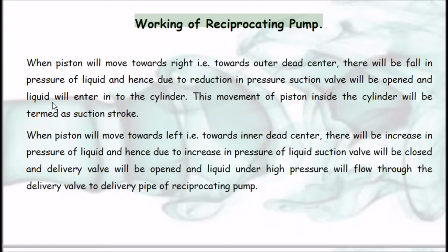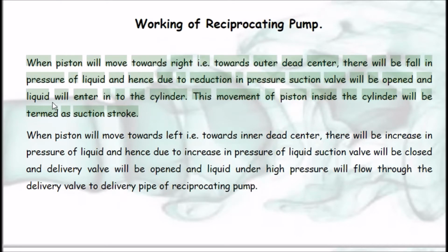Working of reciprocating pump. When piston will move towards right, i.e. towards outer dead center, there will be fall in pressure of liquid and hence due to reduction in pressure suction valve will be opened and liquid will enter into the cylinder. This movement of piston inside the cylinder will be termed as suction stroke.